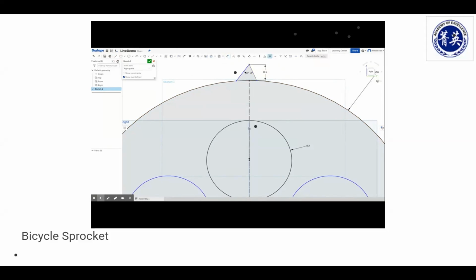Let's also make sure that the 2 legs of the triangle are equal. Good. No gear teeth are really sharp at the very tip, so let's put a little bit of a radius on the very top. Let's call that 0.05. Oops, that's the wrong one. Let's do that again.